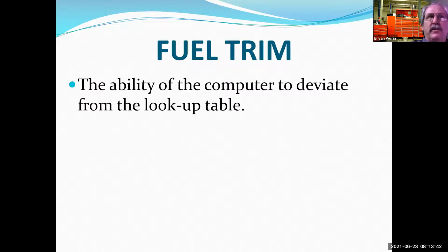But if I don't have something allowing extra air in, then I have to look at why we are not delivering fuel with the engineered amount of on time. So we tend to look at lean codes as we're getting extra air in or not measuring air, or I have a severe fuel delivery problem like a bad fuel pump or something like that, but we really don't think of that finer stuff. So that's why I make that distinction, because it is a really important distinction when you start getting into diagnosis.